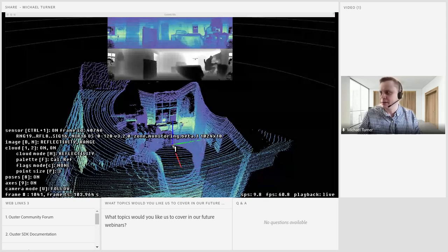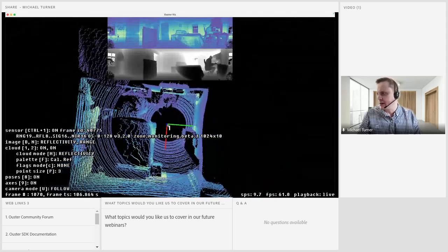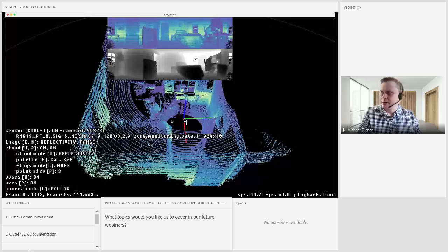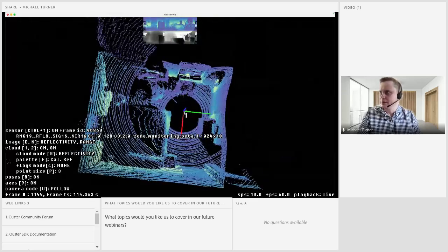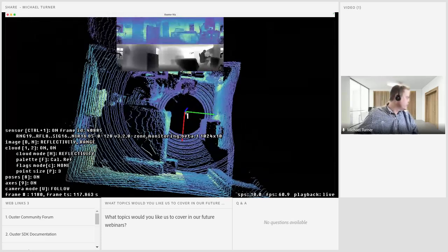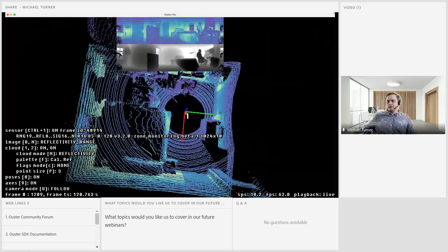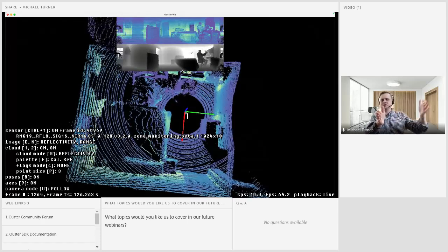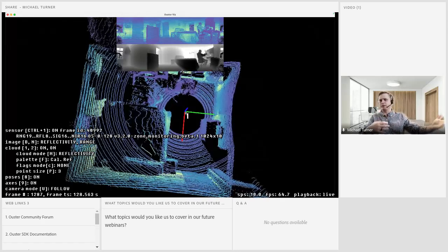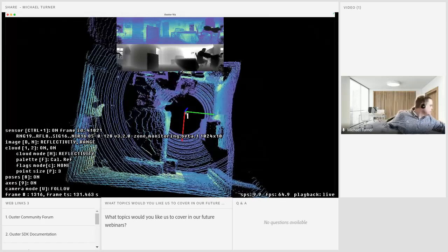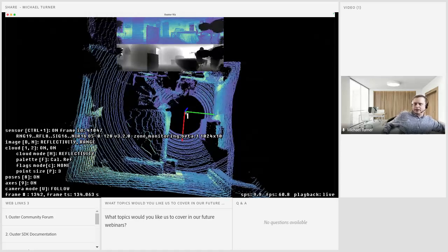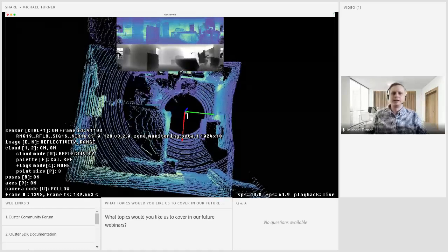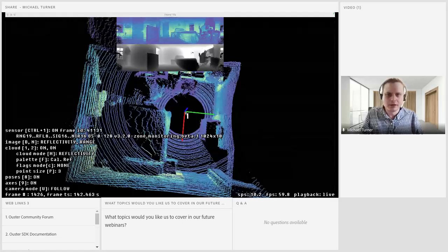Okay, the last little thing to know before I go to configuration: check out that we're visualizing the point cloud with the default settings. So I've got a full 360-degree field of view. And also I wanted to show that by default, there's a 50 centimeter minimum working distance, basically an area before the actual measurements start happening. It's there by default to maintain backwards compatibility. But okay, if you look in the 2D images, it's a little bit more apparent that there are no measurement values. It's just black. So I'm going to change that in my next step here.